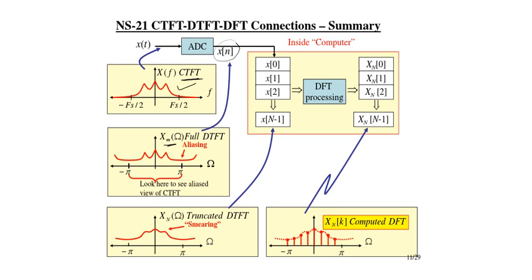So now we find that theoretically the truncated DTFT has these three distinct frequency components kind of smearing into each other, right? So from here you cannot draw any information of three frequency components, and DFT is nothing but the sampling of those DTFT. So you are basically drawing some samples from the DTFT of the truncated version, right? So here you can get some kind of grid error, right? So when you append zeros, basically you can remove that grid error, right? So this we have already talked about. So this is aliasing error, smearing error, and grid error.